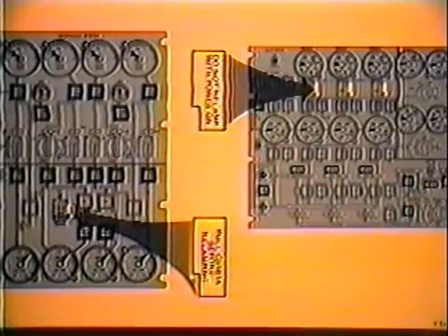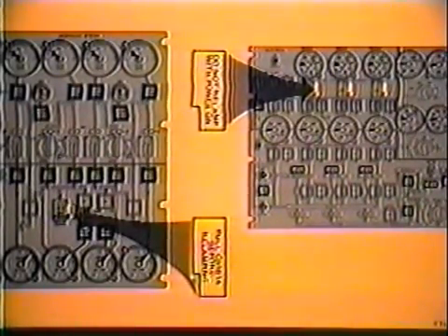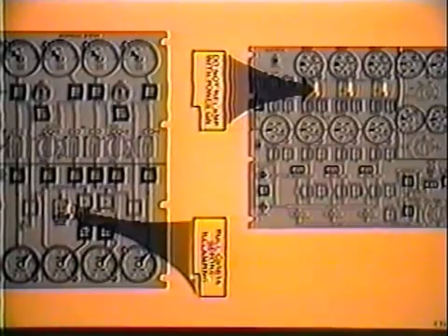Two panels have guarded switches with cautions that must be observed when relamping. The cautions read, "Do not relamp with power on," or "Pull CB 1B14 before relamping."